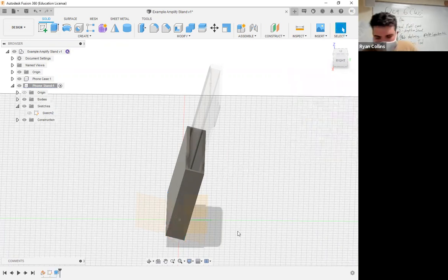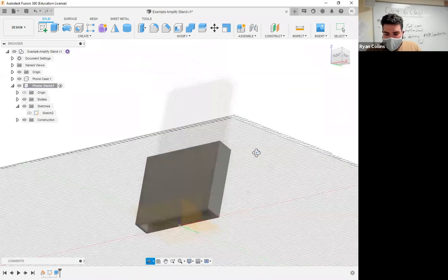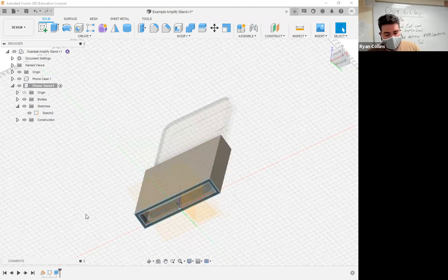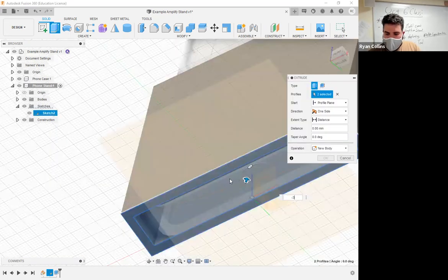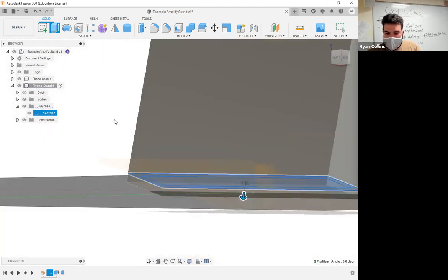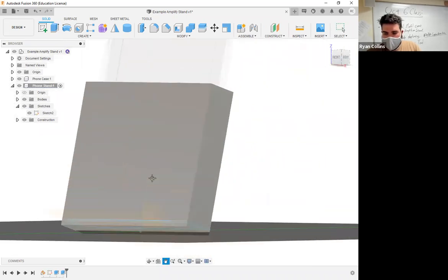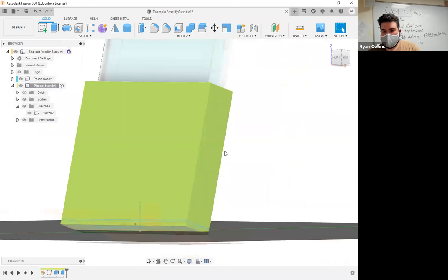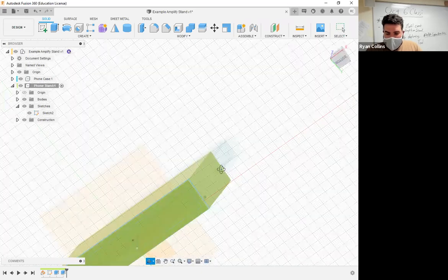Okay. All right. Now it is bottomless at the moment, so I'm going to reactivate that sketch because it always hides everything. I want to extrude again, and this one I'm going to select both of those and go downward about -3. There we go. My operation automatically goes to join. Great. So now I have all of this working as such. Now it's going to start getting confusing visually, so I'm going to switch to pre-assigned colors. So remember, shift in and colors. All right. So this now has a bottom built in there.